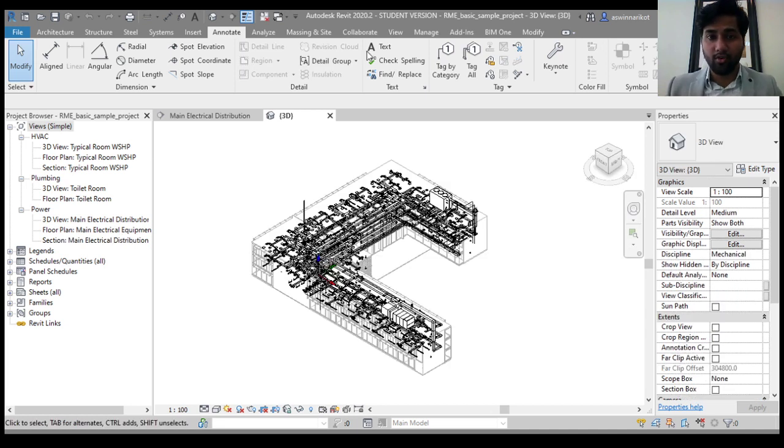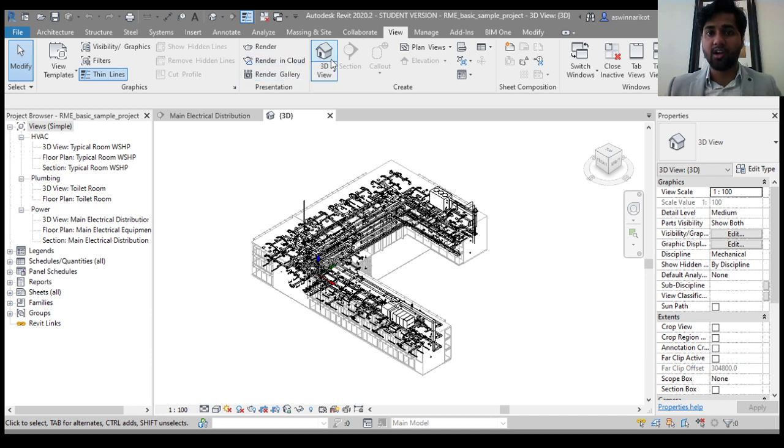So instead of going for the view tab and clicking on the 3D view, which takes a bit more time, you can actually use the options up here so that you can quickly use the tools available in the Revit. And we have different options, and we are able to customize the quick access window from here. So in case you want to add or remove some options or some tools from here, you can do that. Similarly, you can also add more tools into the quick access window.